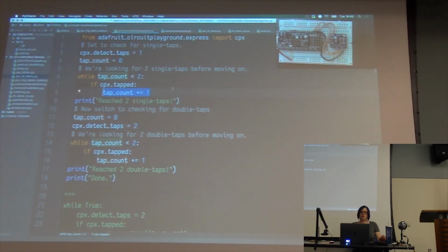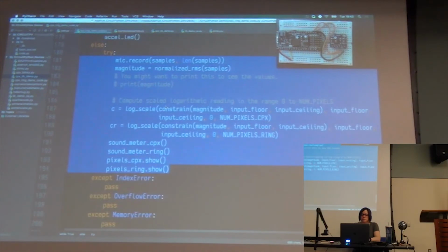But the drivers themselves do have, at least for the accelerometer that's built into the Circuit Playground Express, interrupt registers. It tries to use it for tap detection instead of using a change in acceleration, which is what would happen if you weren't using the accelerometer.